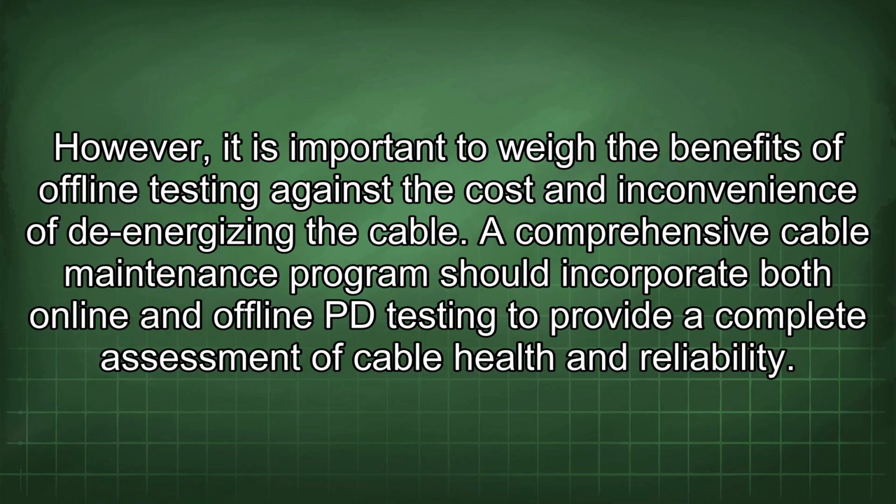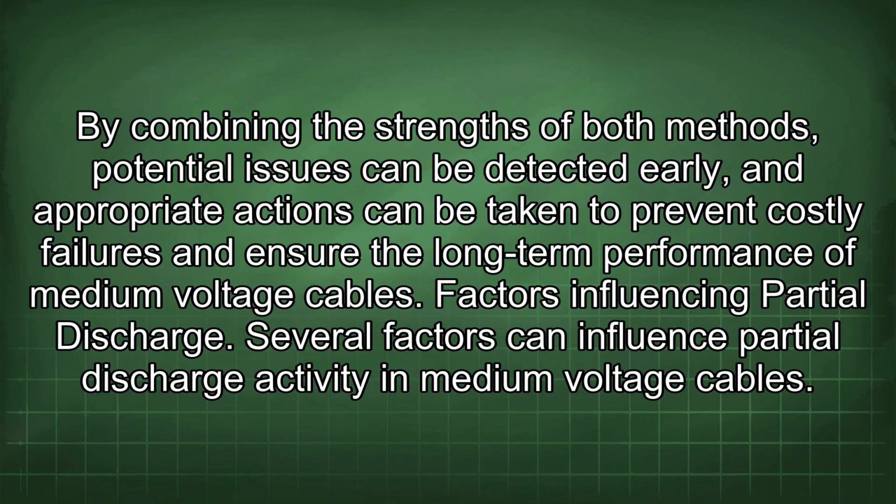A comprehensive cable maintenance program should incorporate both online and offline PD testing to provide a complete assessment of cable health and reliability. By combining the strengths of both methods, potential issues can be detected early, and appropriate actions can be taken to prevent costly failures and ensure the long-term performance of medium-voltage cables.